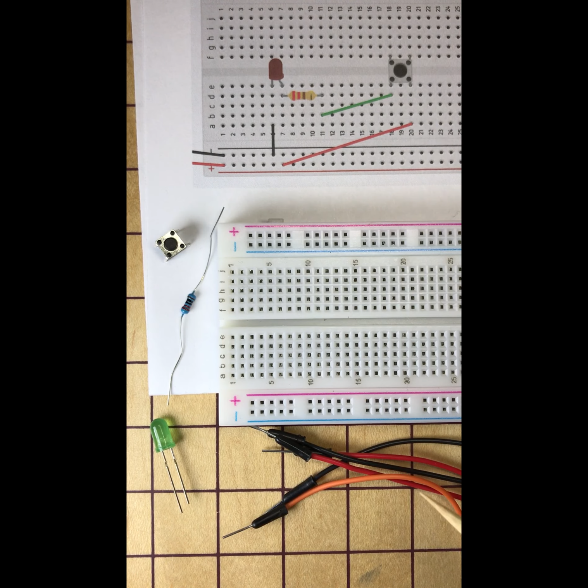I have all of the components here, some jumper cables, an LED light, a 220 ohm resistor, which in these kits they have 5-band resistors, so those are going to be red, red, black, black, brown, bronze, or whatever. But these guys, the colors are a little off, and so just grab the ones out of the 220 ohm pack, and don't worry if you have a resistor that is higher than that. And we got our momentary switch, our little push button switch right there. So we're going to put these parts onto the breadboard.